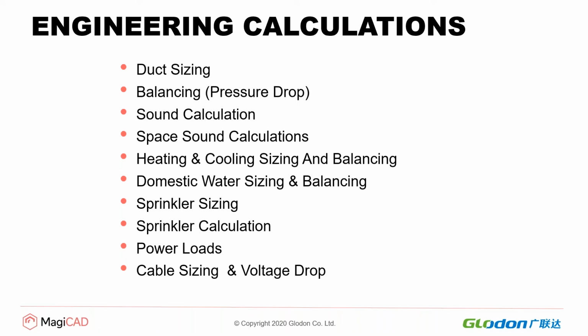If you look at other software like Revit, doing a sprinkler calculation is far away. They may not be able to do the sprinkler calculation for you. But in MagiCAD, you can do the sprinkler calculation by using different standards like NFPA, British standards, or European rules. We also implemented the Malaysian standards and the Singapore standards when we launched into the local areas.